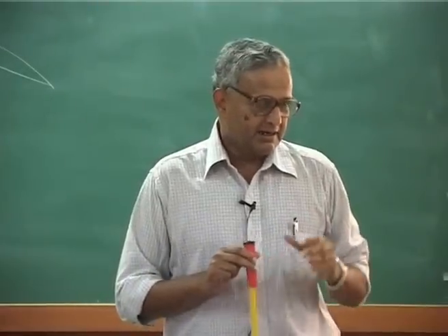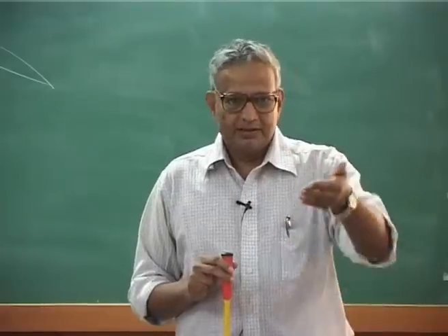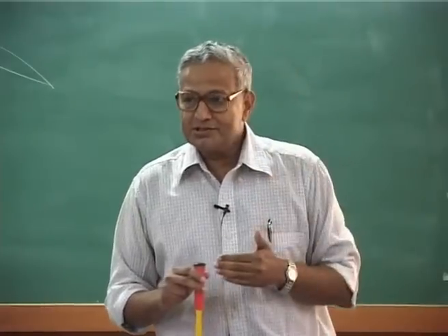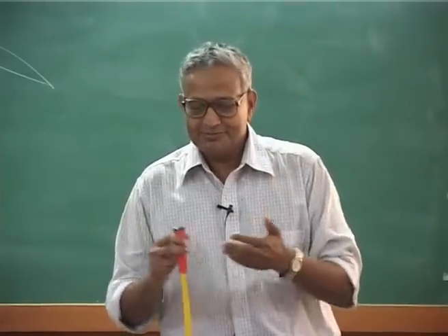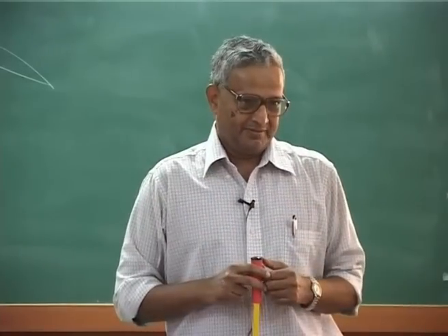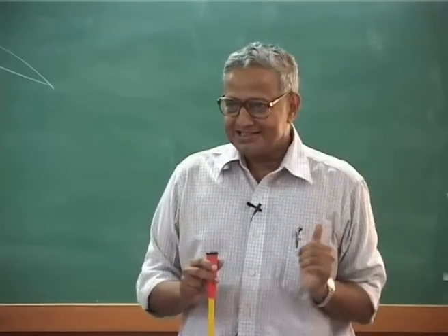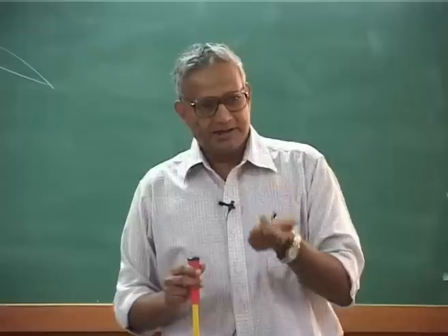But he did not take into account the velocity due to the inflow or the induced velocity. He just took the propeller forward velocity and then the omega r.